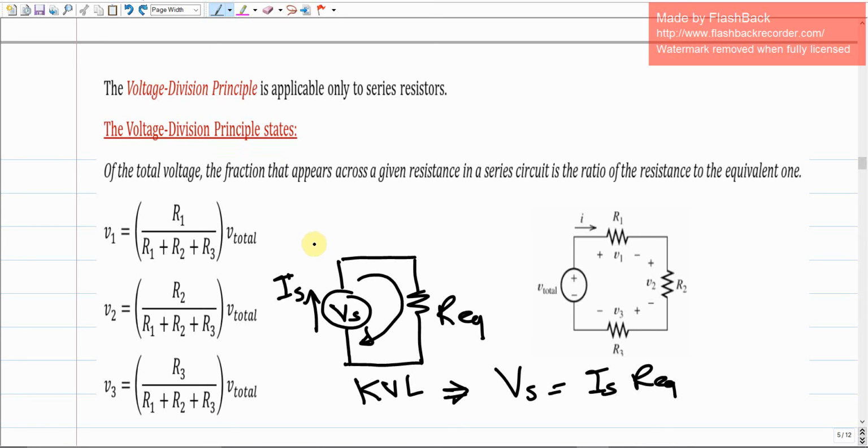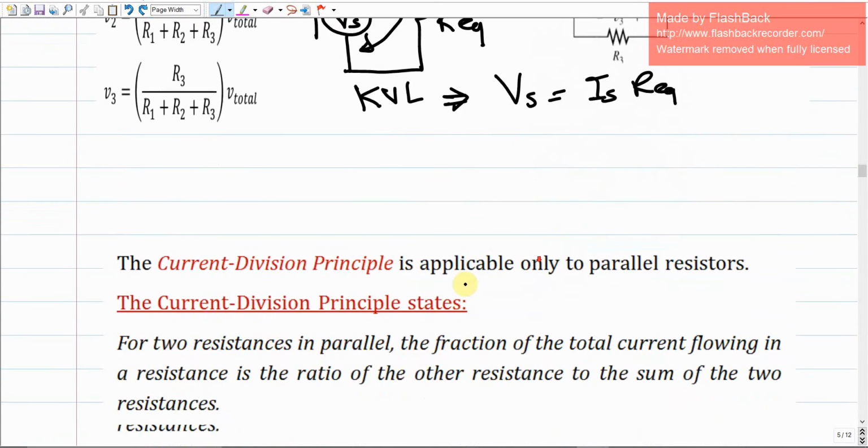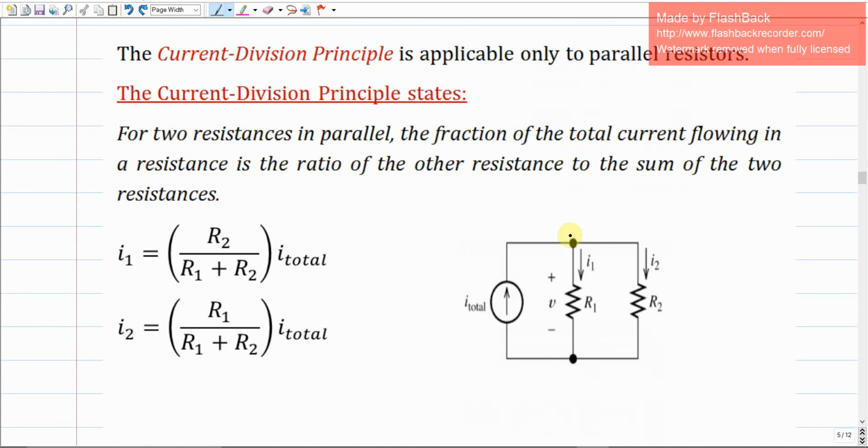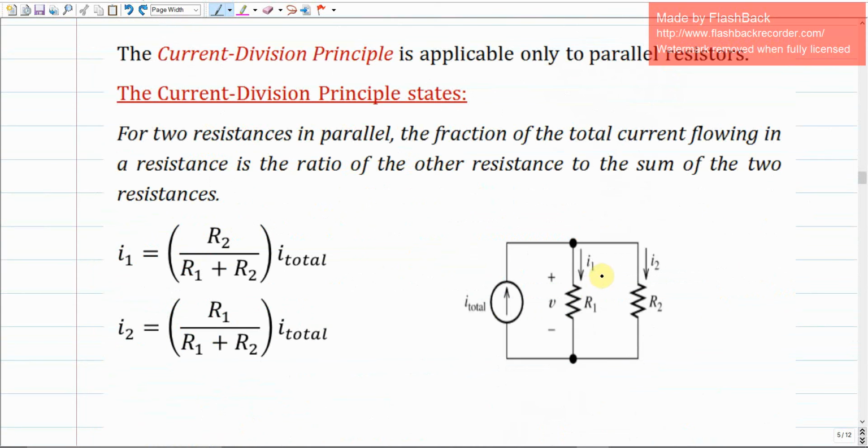The same thing applies for the currents. How about this is the total current? And how about if we have an electrical circuit like this one, and we already have the total current that comes from the source? We can figure it out using this equation from the simplified electrical circuit. So the question is, how much is I1 in comparison to the total current? How much is I2 in comparison to the total current? Because this total current is going to be divided, right?